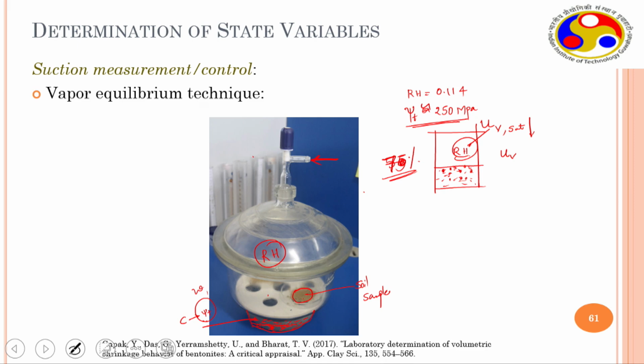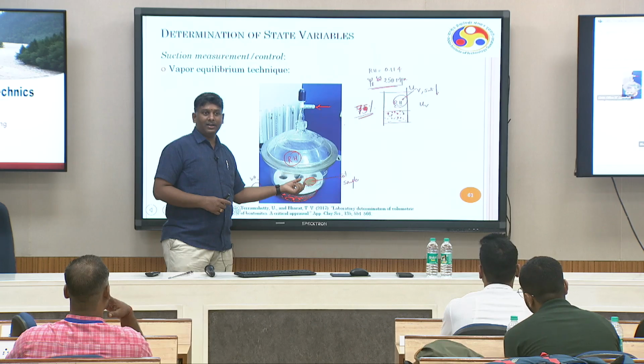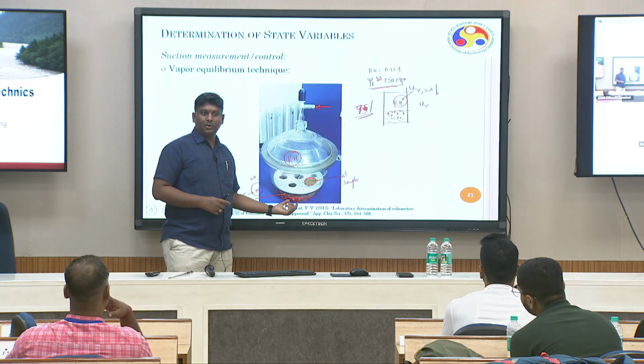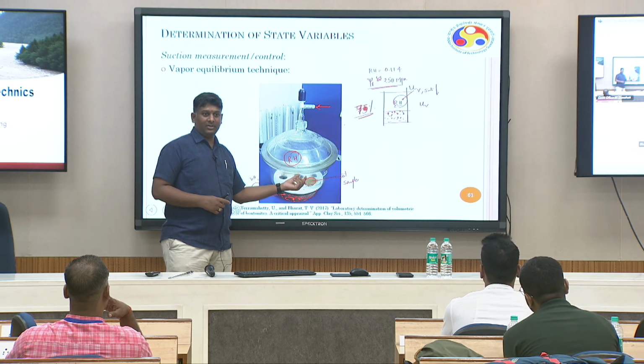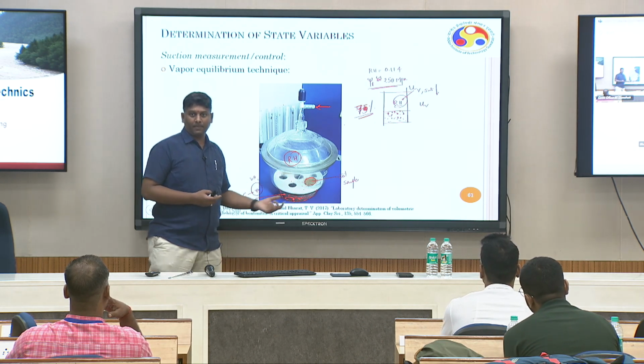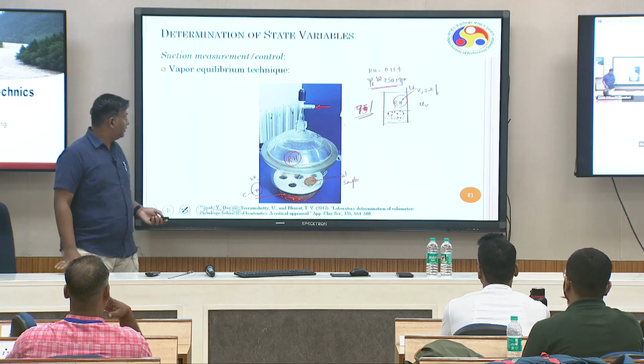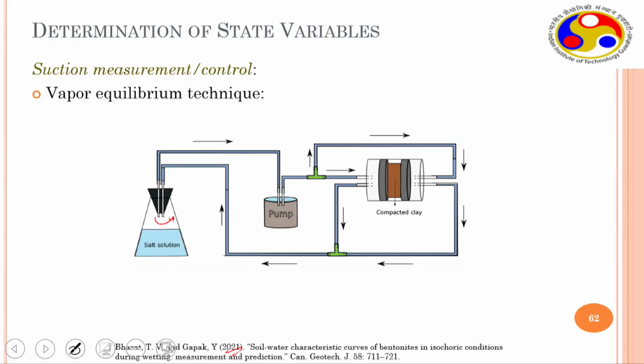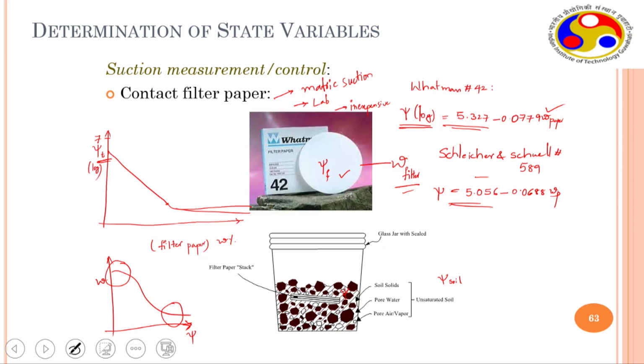If it is water, then the soil gets wet. If it is K2SO4 or something, and if the soil is saturated in the beginning, then the water content will decrease, right? We did this with compacted samples in this manner. We continuously flowed the vapors to both sides of the samples, and this is how the SWCCs of the compacted samples have been established.